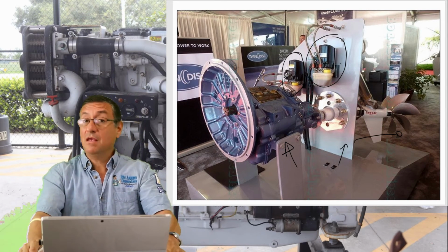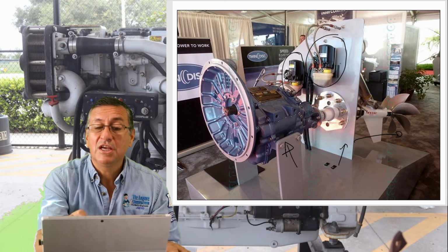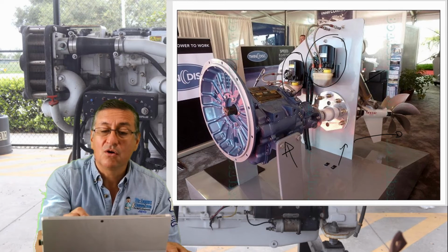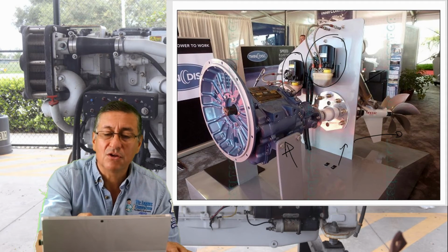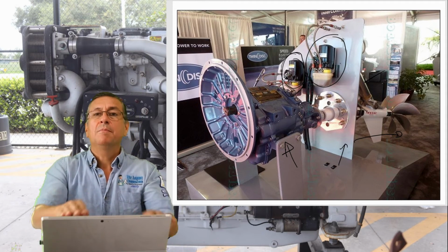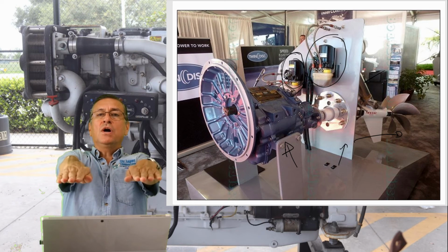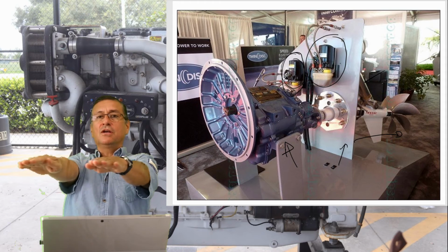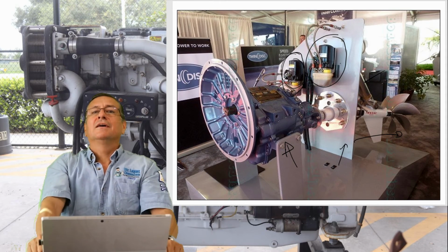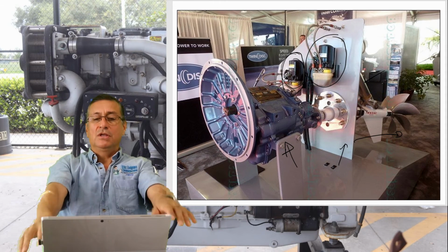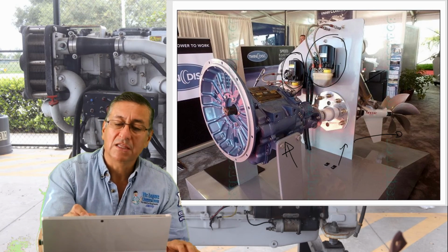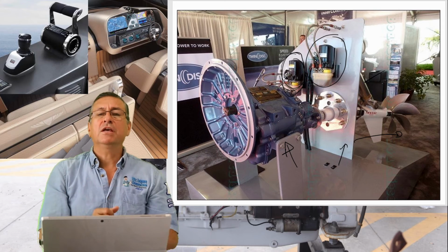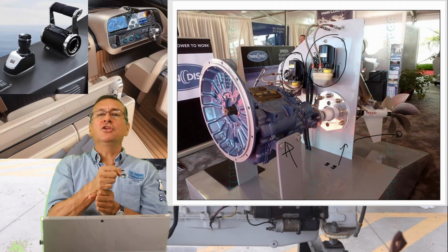And we are going to use the same units, similar units. Look, this one is to control one cylinder or a couple of cylinders, and the other one to control other couple of cylinders, because the jet drive has two actuators to control up and down, and other two actuators to control lateral movement. And the propeller is outside of the boat. Yes, internally, those hydraulic systems are located in the transom.